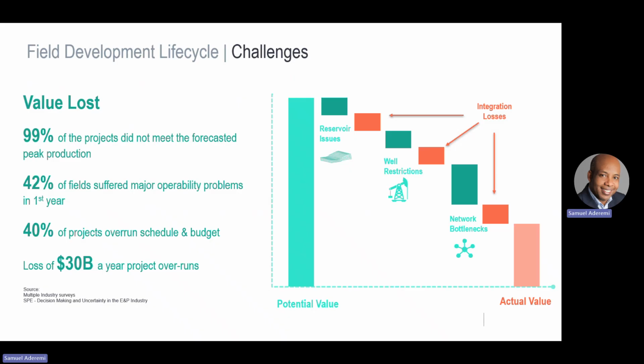Take, for instance, a reservoir engineer may predict a certain production rate from a well, but once that well is connected to the shared production system, the facility constraints are imposed, and the back pressure from the network is imposed on the reservoir side of the well, causing virtual choking effects, because the facility cannot support that level of production. That will automatically reduce the achievable rates.